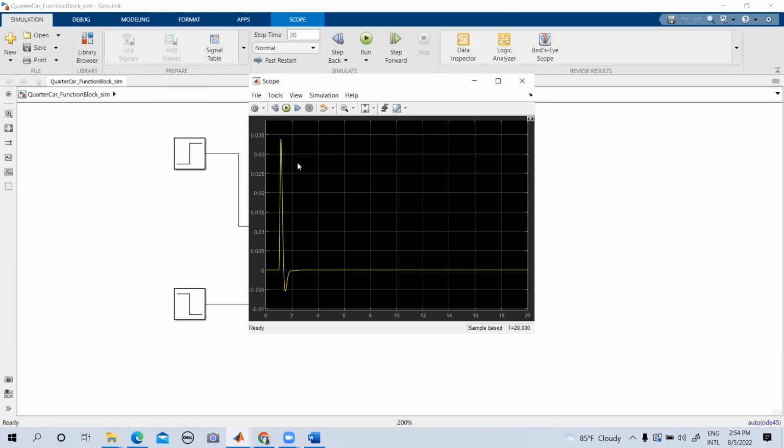Right. So now you can see that the transient has reduced, and the system stabilizes by 2 seconds, right? Earlier it was like that, but you can see that there's a high impulse in the amplitude of the signal, though it's still not up to the point that it had earlier. So the system is a bit more optimized now. Earlier I think it was above 0.035, between 0.035 and 0.04. So this is a smoother system.